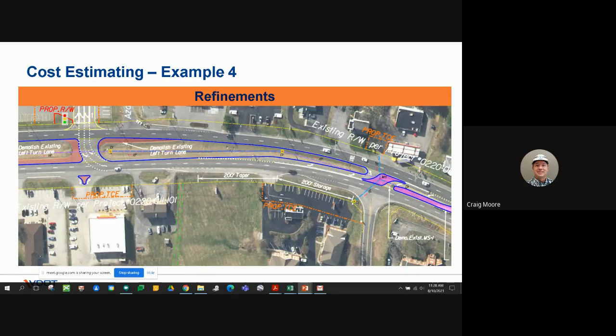We have this DI here to the right of that business. How are we accessing and getting to that? That's part of the reason that proposed temporary construction easement is as it is, so that we can best address the stormwater management. Also on the north side, you see another temporary construction easement associated with stormwater drainage.